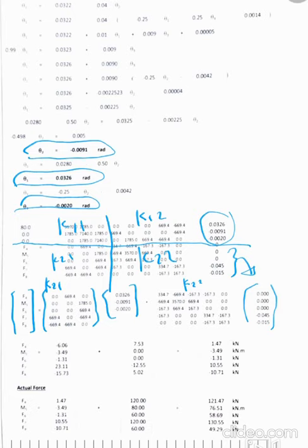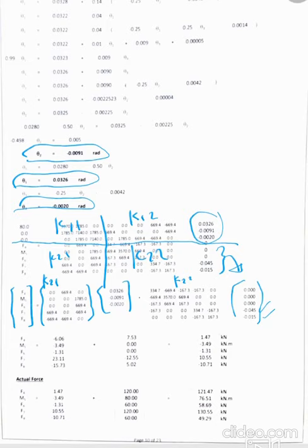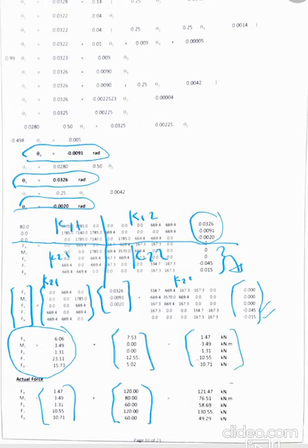Okay. Don't forget the settlement. Settlement should be minus, because settlement pulls the structure in the downward direction, so you should put minus. And then find the values of F and moment that are unknown. Then add it with the matrix of these. All of these are matrices actually. It's unclear for you. Okay.